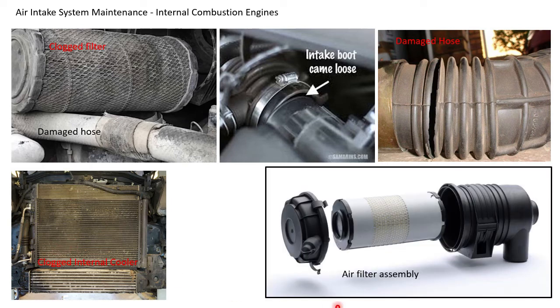Then afterward, the another one is the clamps. If this is the air filter assembly of a particular engine, this is the housing, this is the filter element, this is the cap. We must ensure these clamps, whatever is there, 3 or 4 depending upon the filter type, are well secured in the housing. Missing clamp, cracked clamp also leads to the dust entry.